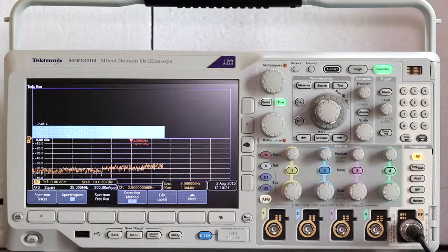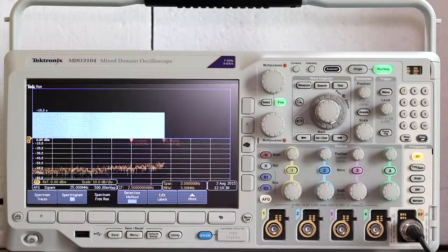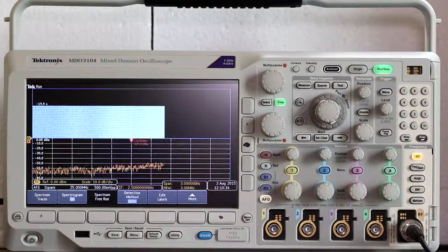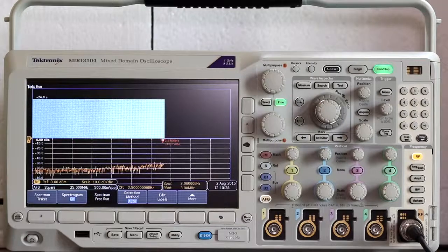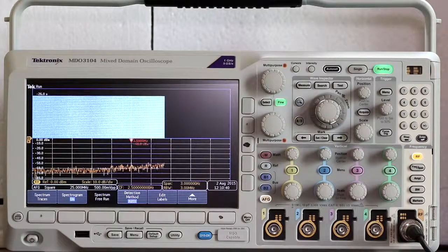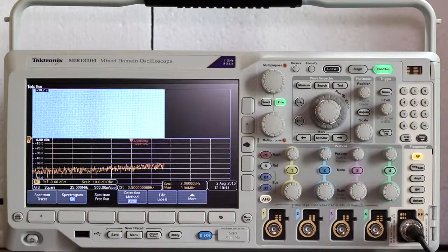There is the spectrum analyzer display showing the 25 MHz signal. The y-axis still shows amplitude, but in power rather than volts. The spectrum analyzer vertical units are in dBm, with default reference level of 0 dBm being at 1 milliwatt at the top of the display. We are now looking at a logarithmic scale.